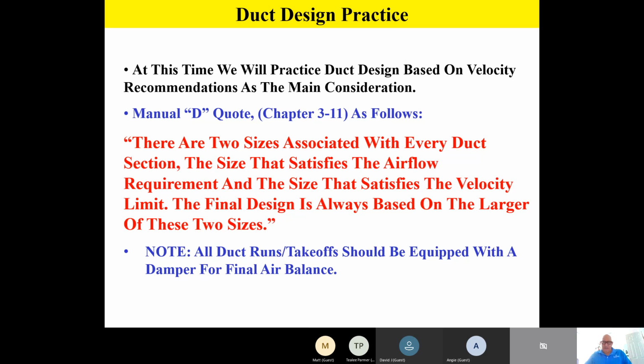And so there are actually two methods to design a duct system. The one method that's used a lot in our industry is what we call the friction loss method, also called the total loss method, where you look at the fan capability and then build a system to use up all the capability of the fan as far as moving air.